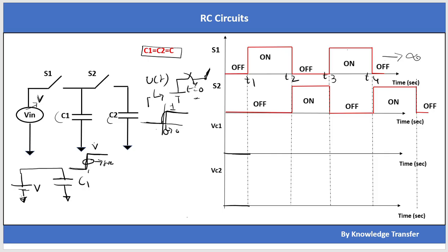That means this node is 0 volt. At t equal to t0, because I am turning on this switch, and assume this is an ideal switch, the voltage at this node suddenly goes from 0 to 1 volt. Let's assume this voltage is 1 volt, so that I can make this unit step signal by using a voltage source and a switch.